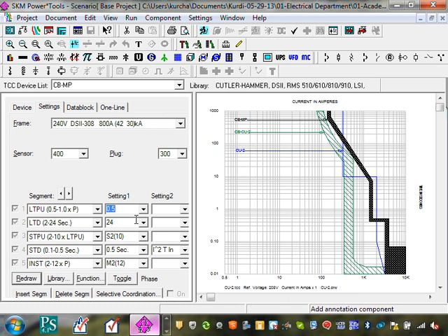The code requires these dials to be locked in, accessible only to qualified people, or put behind covers that are covered and bolted, so people don't accidentally start adjusting them as they move around, as they sweep the electrical room and adjust the circuit breakers in between. Okay, so that's what you're looking at. That circuit breaker, long time pickup, is the big component here. I want to take this one back. See how easy that is?